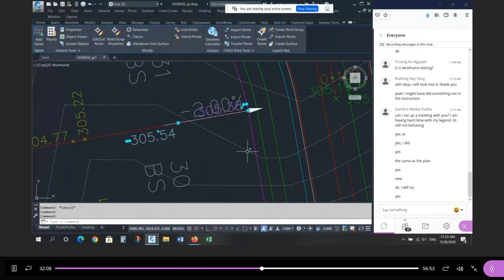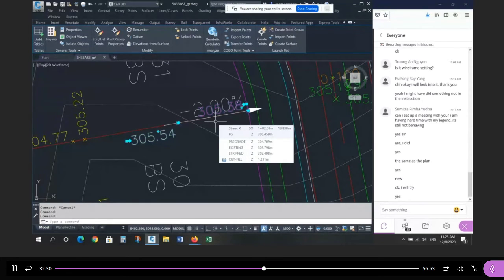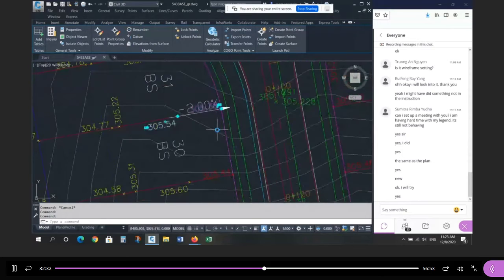It's really kind of a trick. It's the slope on the surface between those 2 points. These 2 points define the surface, and then I can label the surface, and it'll show the slope between those two locations. So that label is actually the surface label, but now it looks like I've labeled the slope between the 2 points, and that's the trick.